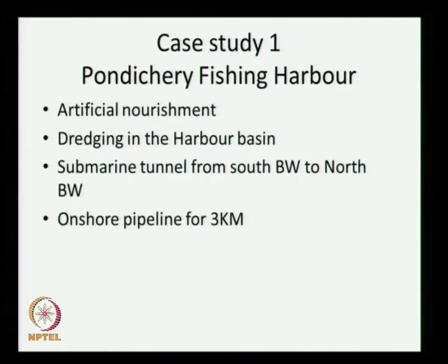So we are going to study some case studies. We are going to study 6 locations, all of them are on the east coast, because on the west coast the littoral drift is not from south to north. Some places it is south to north and most of the places it is from north to south. This is because of the topography, the bathymetry and the direction of the waves.